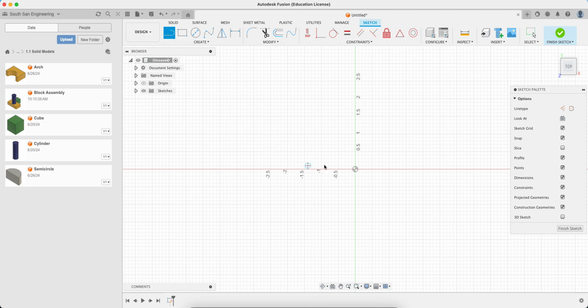So I'm going to choose line, and I'm going to come draw down here the triangle on the side that I took all my measurements off of, right? So again, mine is different from yours. Mine's 3 inches long. And notice when I click to make the 3-inch line, I have this other line that just starts immediately from when I click. So I don't have to click twice.